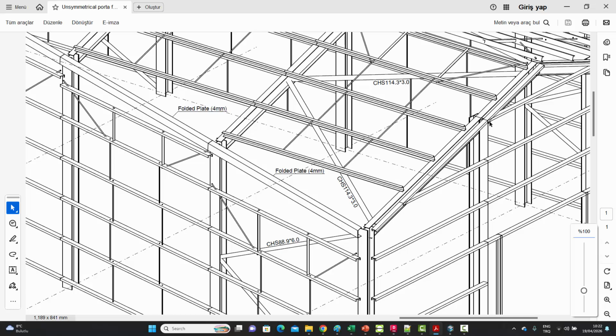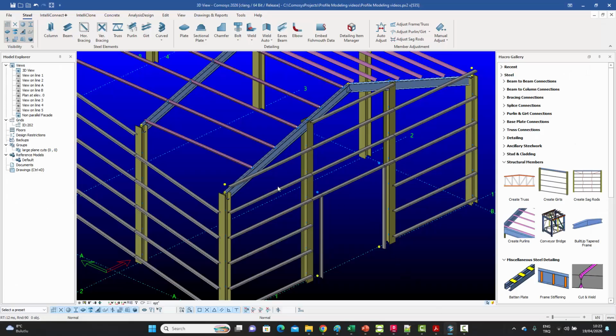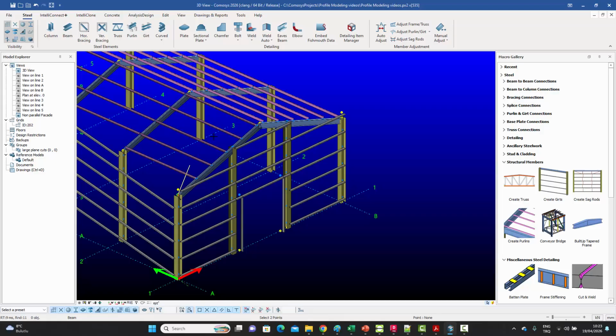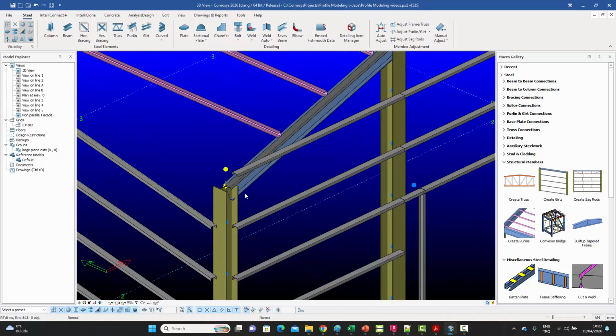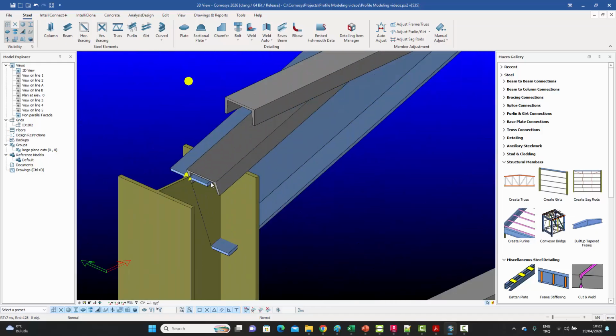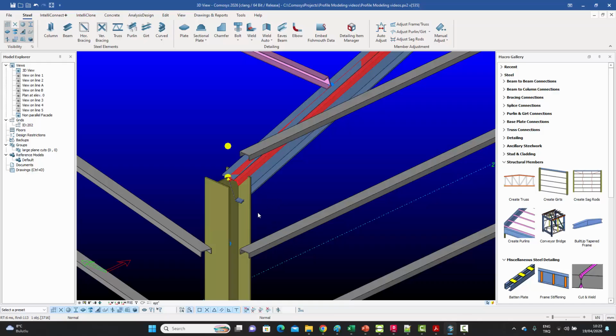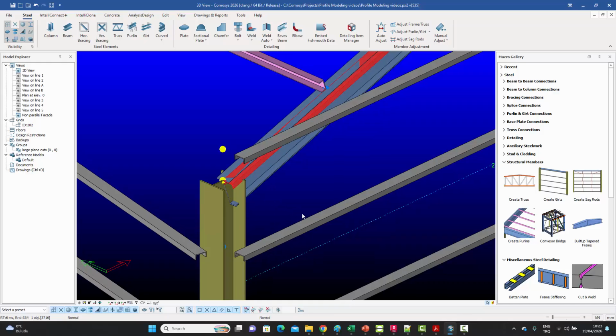This one. Now, when we're talking about this one, normally the first thing which would come to mind, since we've been mentioning this whole thing about making sure your definition lines are correct and then you offset them, is that we go to our girts command and we enter that girt along the roof beam, basically, like that. And then basically you bring it down like that, and you give it an offset of 150, and you bring it so that the outer face is the same as the other girts.